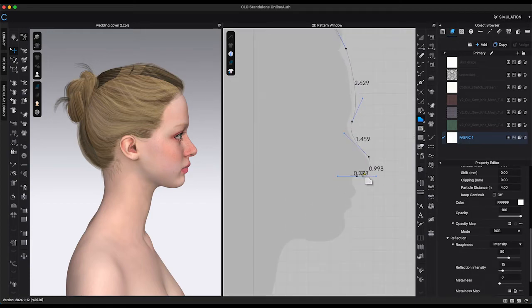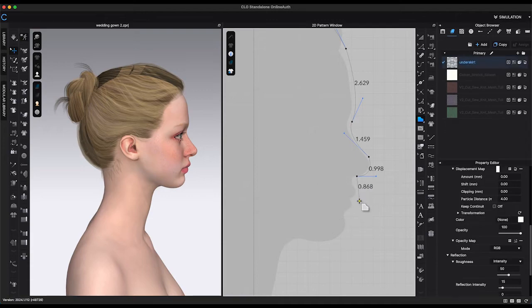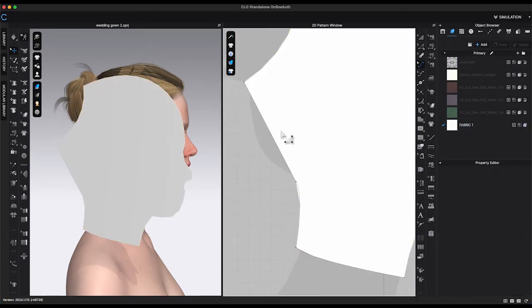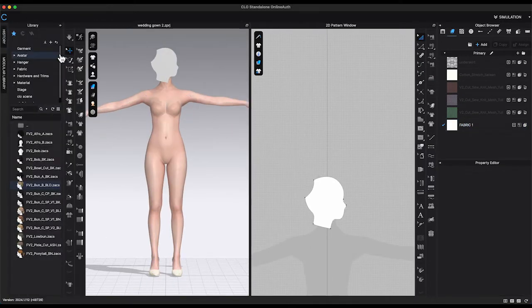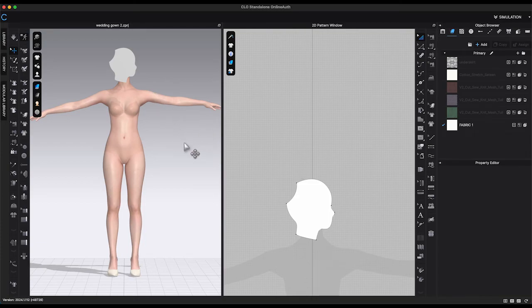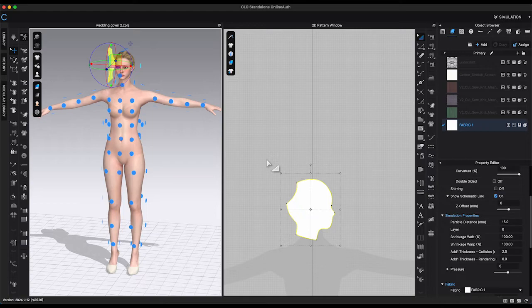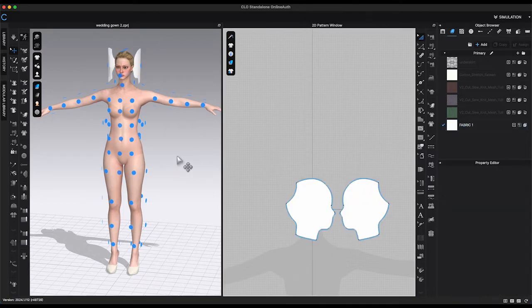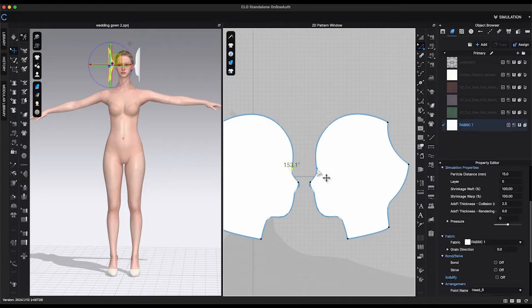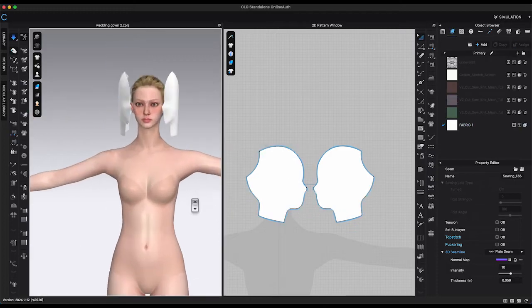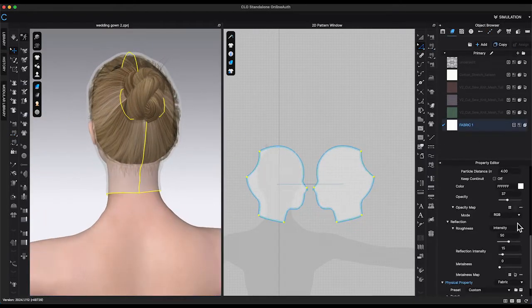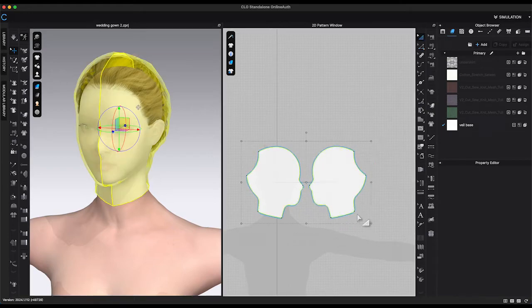Use the Polygon tool to trace the shape and generate one side of the cover. Then right-click and choose Symmetric Pattern for the other side. Connect the two pieces together and simulate. It fits well. Freeze the cover.